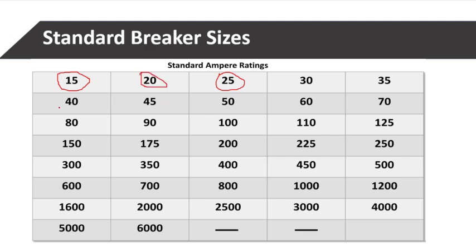Now when your client puts on this load, everything at once, and this load starts drawing this massive 25 amps current at once, and your breaker is only 15 amps. Because this 25 amps current cannot pass through this breaker without the breaker tripping off, the breaker will keep tripping off, and your client will keep calling you that the light is going off in the house.